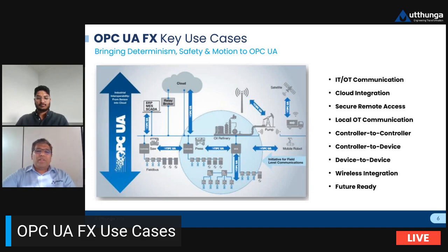OPC UA FX mainly operates between controller to controller, controller to device, and device to device, and all the other OPC UA technologies related to PubSub and client server would allow you to integrate the rest of the systems with the field level systems to have a very seamless IT/OT integration from sensor to cloud, and the whole system from end to end has very robust security features